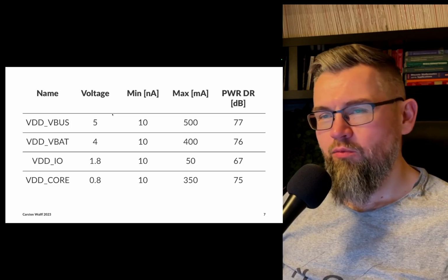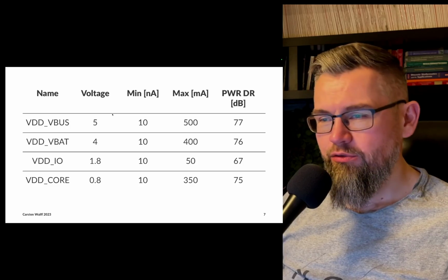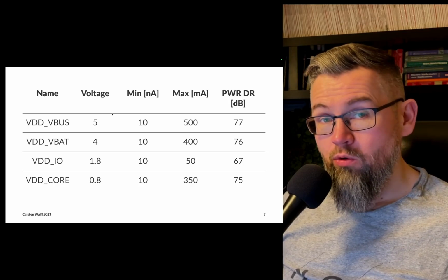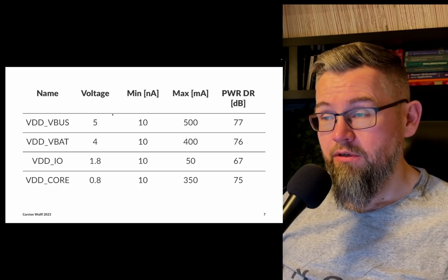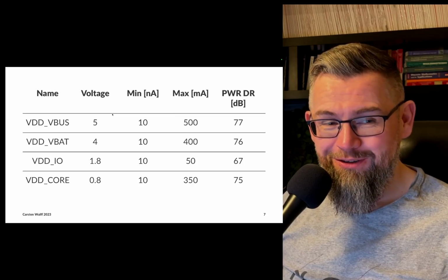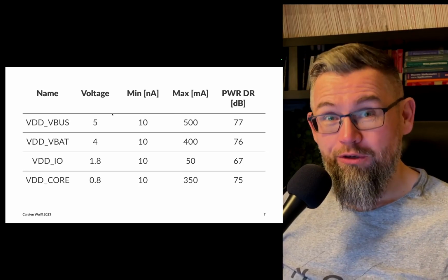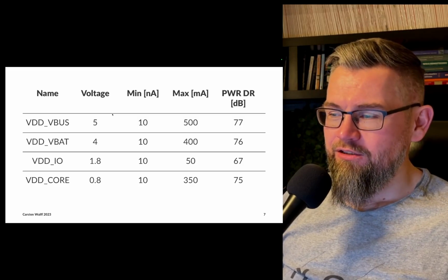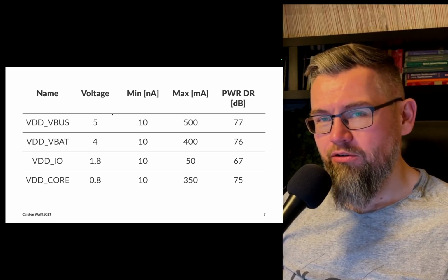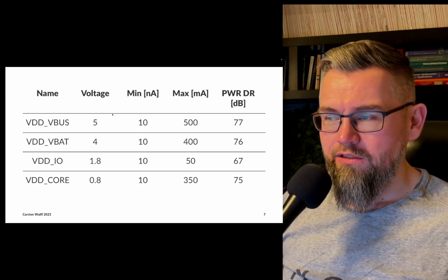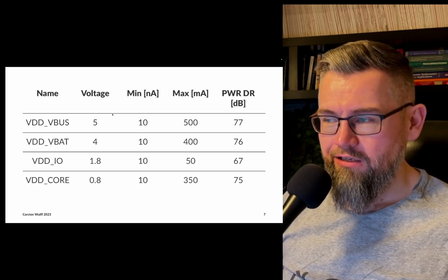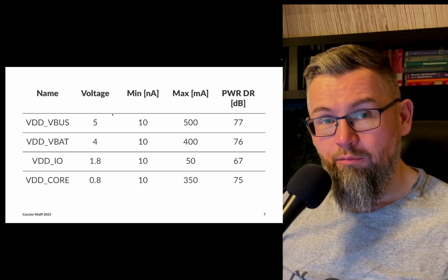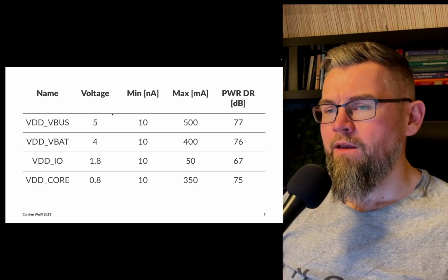And then maybe when you're transmitting or doing a lot of computation, the current consumption can go all the way up to a few hundred milliamps. Of course, if you're on a CPU inside a computer, we're talking amps, a lot of amps. So the dynamic range of these power subsystems is quite significant. I mean, this is 10, 12 bit type of resolution. So it's not easy.